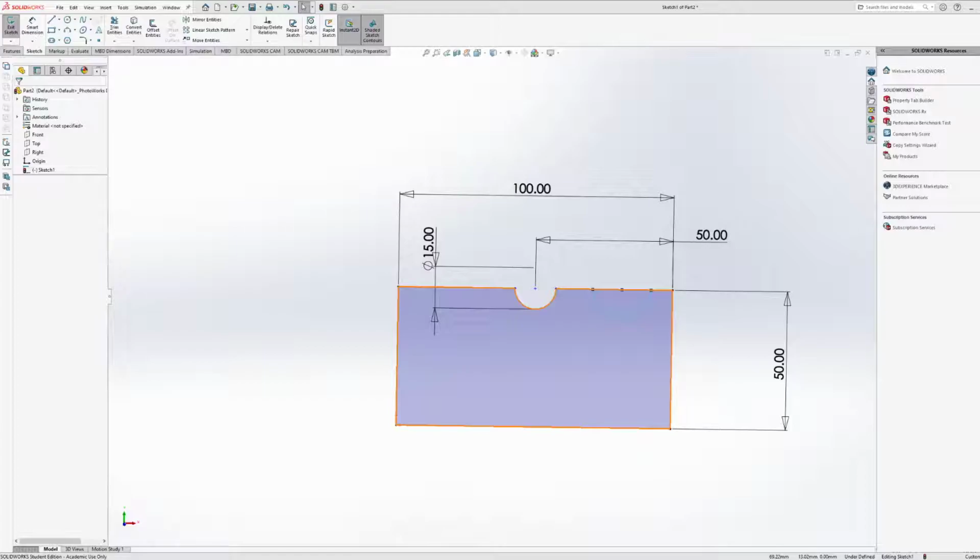The first problem, how do you move it around? How do I move it to 1.5 inches? So real quick, Nathan, when you ask how do you move it to 1.5 inches, I would recommend that once you've created that base shape, the half pipe without that extrude cut through it, you go back to your sketch or create a sketch on a flat surface, preferably.